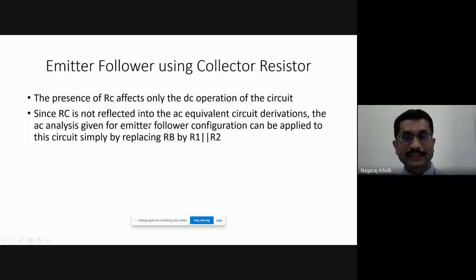Just we have to replace RB by R1 parallel R2, and that will give us all the equations for the performance parameters of the emitter follower using collector resistor.